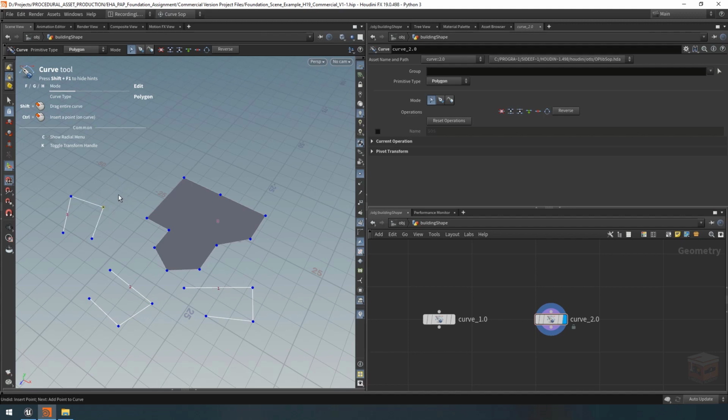But if you want some more control over this, you can also use the widget. So if you press the K button, it will bring up a widget, and then you can move it around or snap it to one of the elements in your screen. If we press the buttons here on the left, or we hold the X key and we select, for example, grid snapping, then we can now snap to our grid.